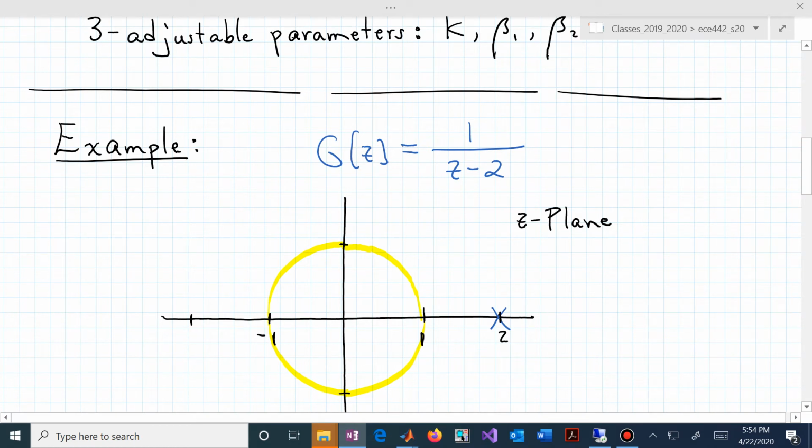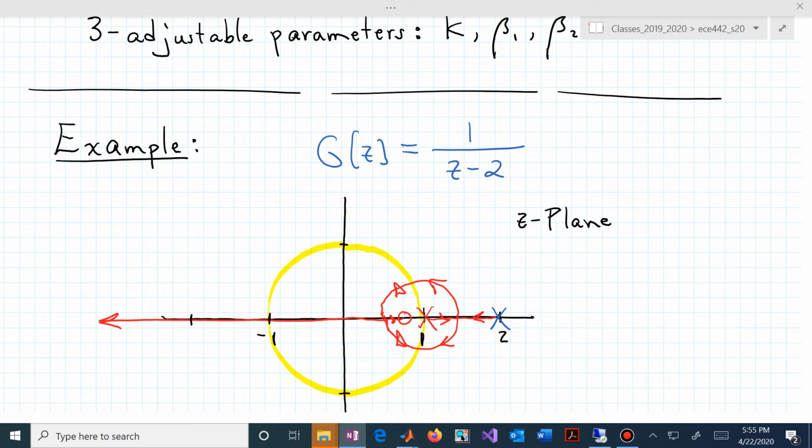Well, now if we introduce a PI controller, which we have done for this system, now we can have the two branches meeting each other. Then they will circle around. This is the scenario, and those are supposed to re-enter at the same place. This is now our two poles to the right of the 1, 0 structure that we're used to seeing. And now we could crank up the gain to get us to those triangle locations. That would be a PI controller, and that would work.